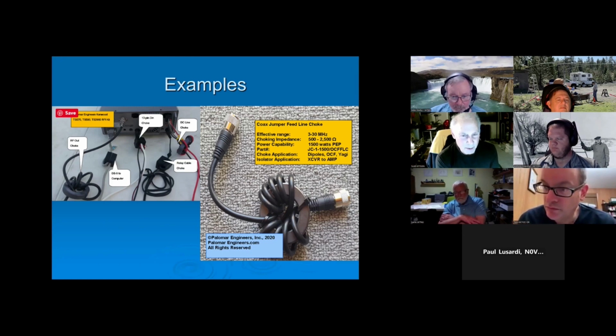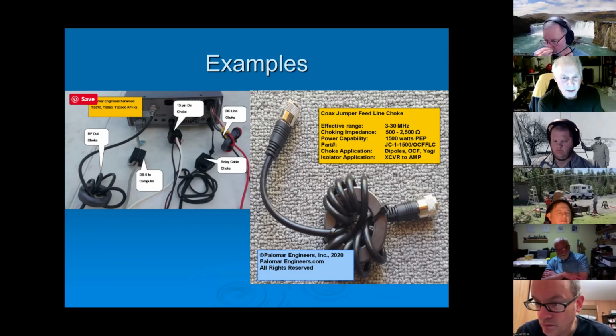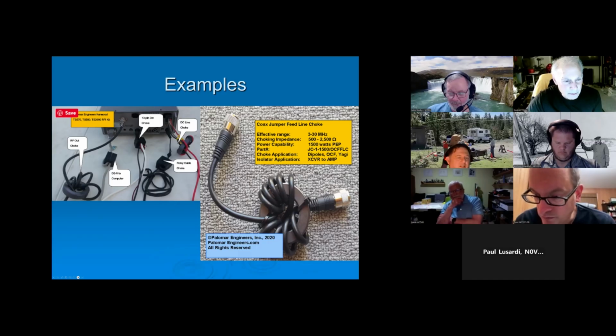But if you've got common mode current flowing on the outside of the shield, then there's nothing to compensate that, so that will radiate. And not only radiate, but you can induce common mode current, and that's how we pick up noise and things like that. So that's why the inner conductor is not affected, as long as the shield is good. If it's a crummy shield, of course, it won't work as well. And there is a lot less surface area on the inner conductor, so that makes a lot of sense.